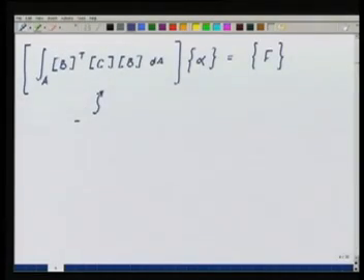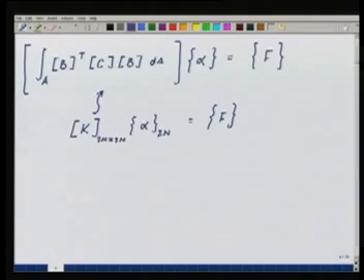This is now the global matrix K, which is of size 2n by 2n. Okay, this is into alpha of size 2n, and this is f, which is of size 2n. So the global stiffness matrix comes out of the integral over the area of what we call the B transpose D B matrix. D is generally used as the material matrix instead of the C that we have used here. Okay, that's just a naming convention.